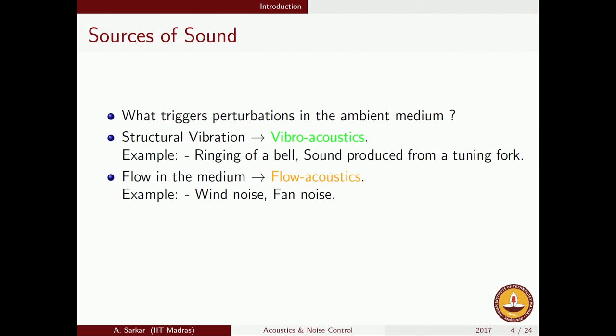So, what happens is that these fluctuating quantities are transmitted from their point of generation to far away field points, and that is also a process in which sound can get transmitted. So, the point is this: the source of noise this time is the turbulent fluctuations which happen in the turbulent boundary layer, but then these fluctuations are eventually conveyed or transmitted through large distances in the form of acoustic wave propagation.